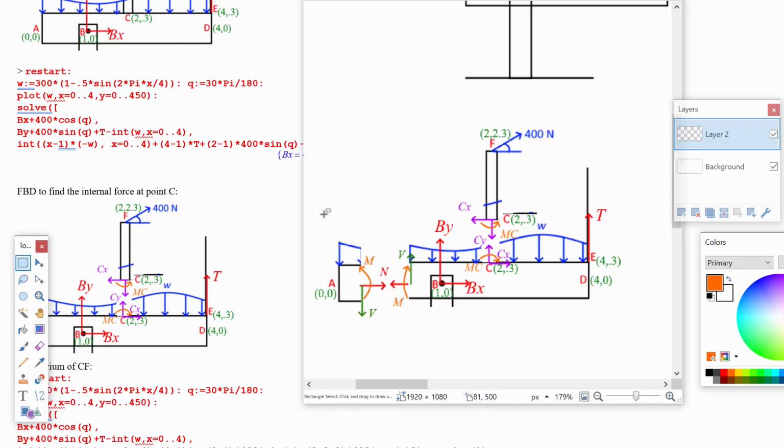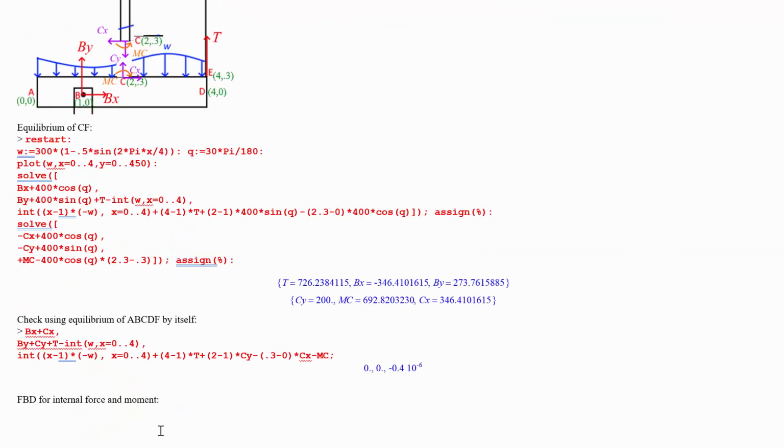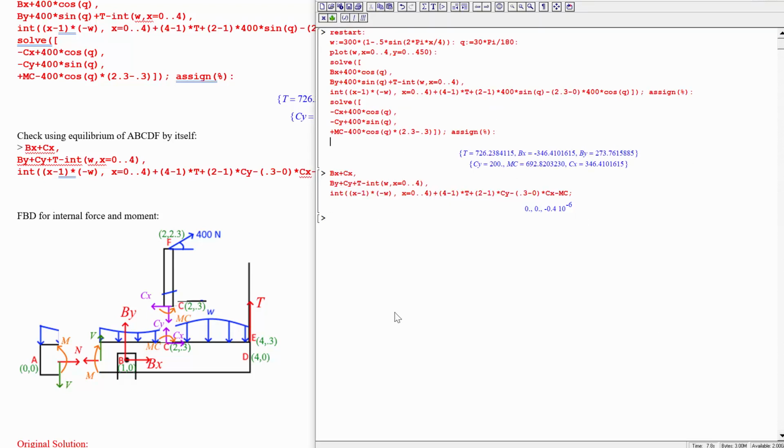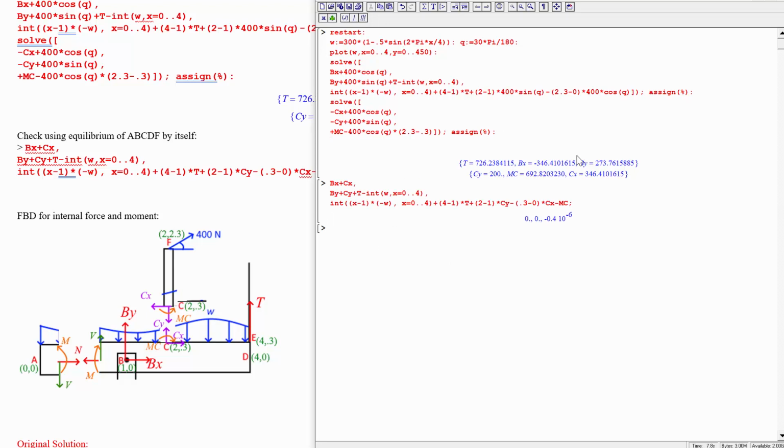Okay, so with this in mind, we can now write down what's going to be going on for building up the shear force, the normal force, and the bending moment. And the way to do that is to start defining them. So let's see, again using Newton's second law. Let's start off with the normal force. Normal force is going to be 0 until we pass point B.